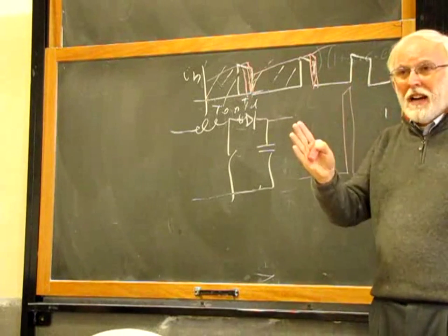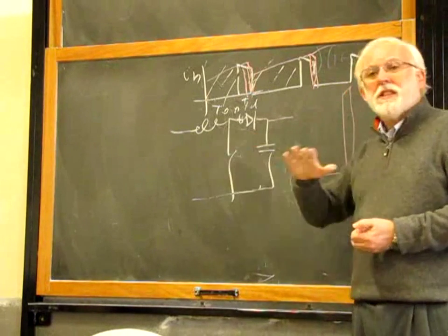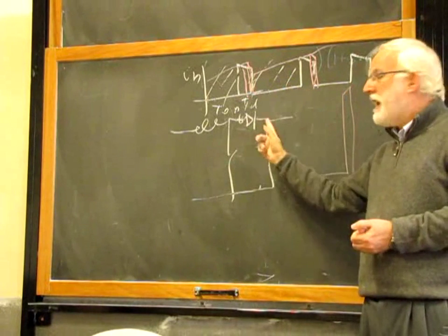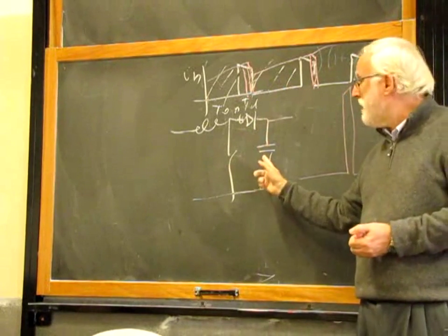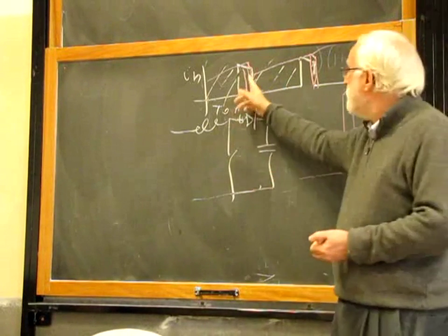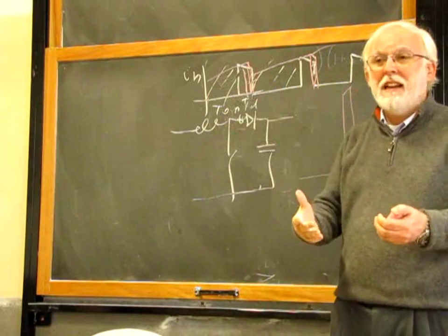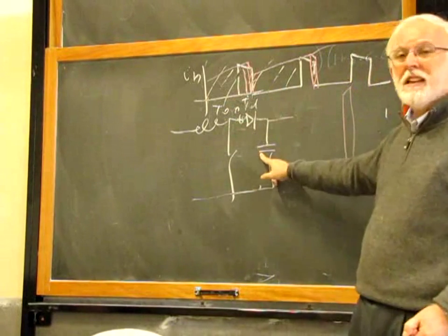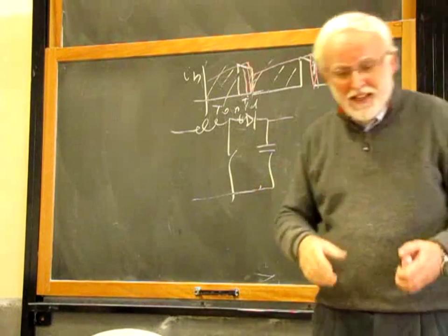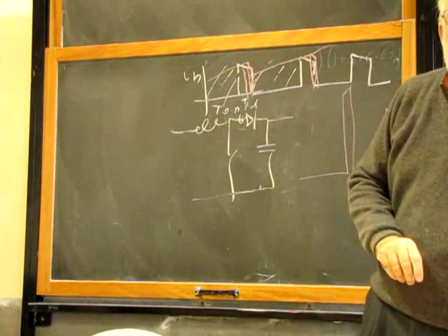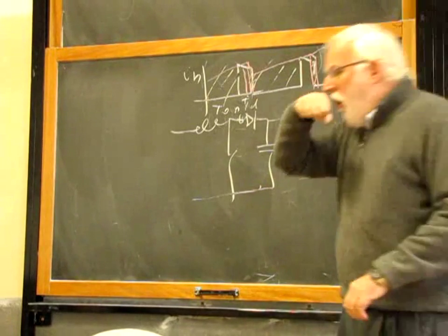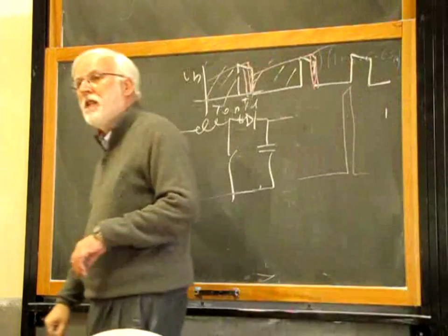So you increase the duty cycle, the inductor current goes up slowly, and the time that you have to discharge on the capacitor decreases immediately. So the first effect of increasing duty cycle is giving less energy to the output. And if you give less energy, the output voltage goes down. This is, let's say, the hand-waving reason why there is a right half plane zero in the boost converter. Okay, see you Friday.